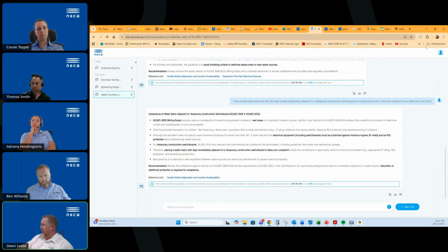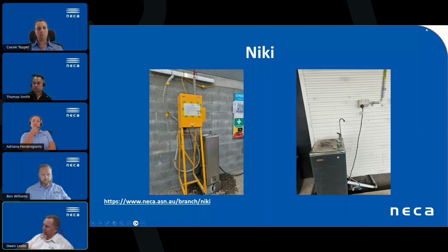If I go back to the image in regards to that, I'll just close that down. You can see that's the 5-pin plug outlet, the 3-phase outlet, and it's just over the top of the water fountain. So if you're going to use that, you're going to be dragging a cable straight over the top of the water fountain, and that tap can shoot straight up into it. So there could be water ingress if the shield happens to be broken, the cover that flips down on top of the 5-pin plug, which it wasn't in this case, but they have been known to break over time.